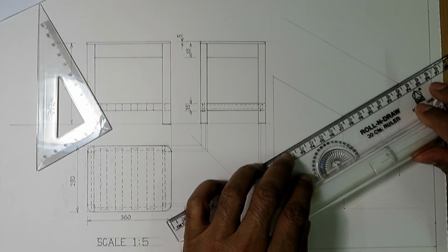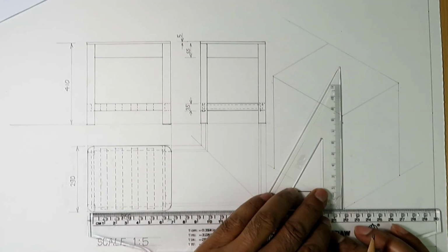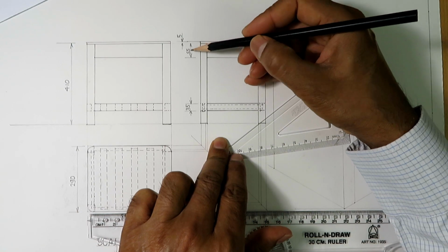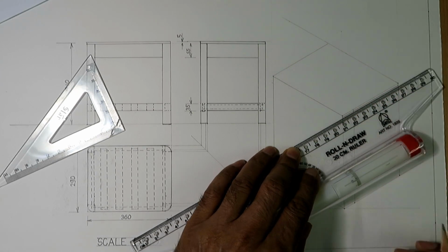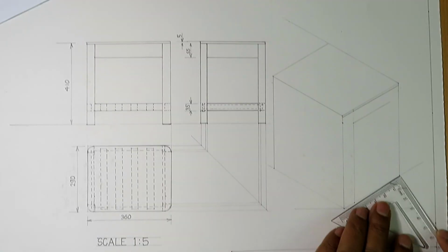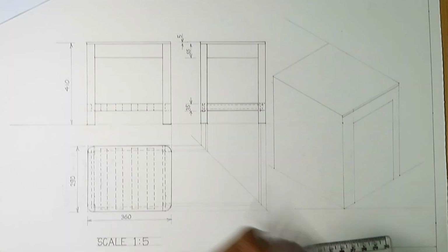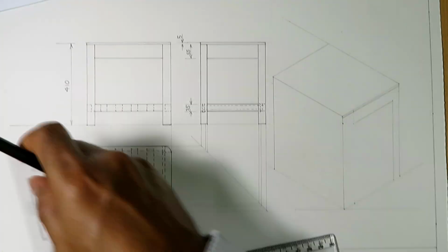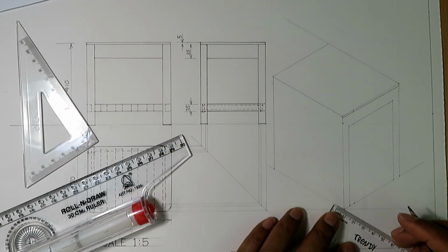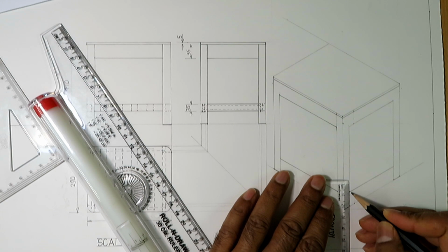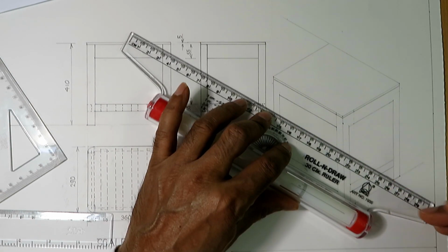So this is the isometric view of a cuboid with the same height as the stool, and the top surface has a dimension which is similar to the top seat of this stool. So whenever you can fit an object inside a cuboid, it is recommended that you start with the cuboid. So you draw the isometric view of the cuboid, and then you draw other dimensions so that they all fit inside this cuboid. You can watch another video in this channel on how to draw isometric view of any object.